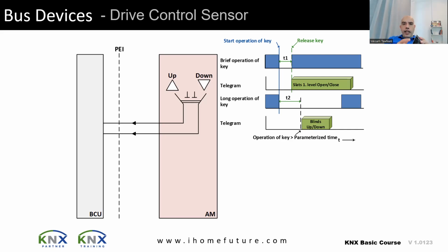Okay. So again, I have the shutter or the curtain, and then I do a short press. It's moving up. I remove my finger. It will keep moving up until it opens. If I want to pause it in the middle, I don't want it to open or close the entire way and want to pause it in the middle, then during the movement, I do a short press. If it is already open or closed and I want to move it in the reverse direction, but in small steps, then I keep doing short presses on the button.